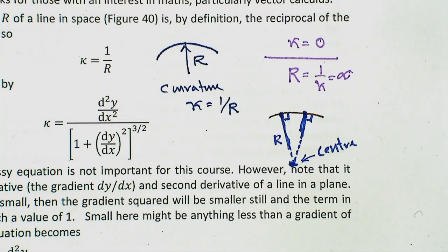So this formula, again, we looked at here, and we introduced you this concept of the curvature with the radius of curvature r here, and this particular formula that we came up with, if I can make it bigger, that moment over second, bending moment over second moment of area is sigma over y is E over r.